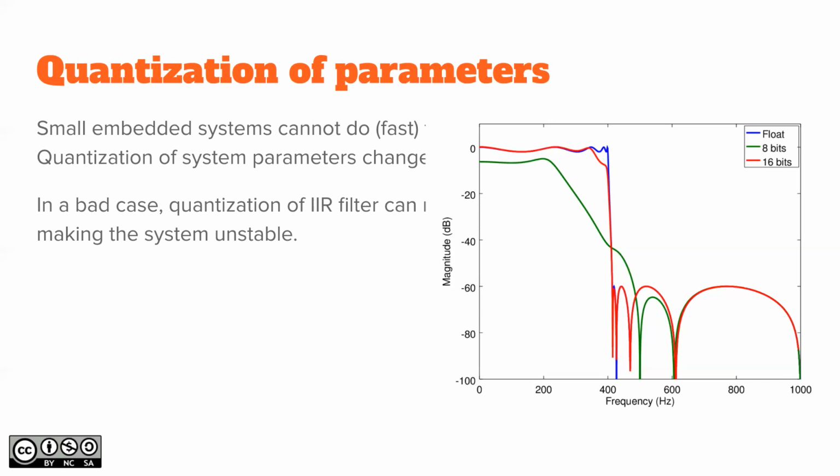which means that for multiplication, you do integer multiplication and then fix the decimal point. A very simple operation, especially for the fixed point digital signal processors, where this fixed point presentation is the native data presentation.